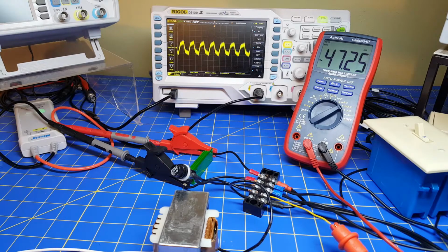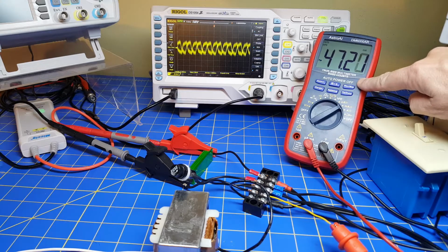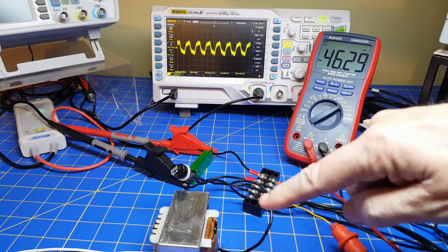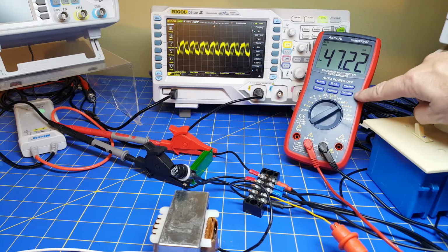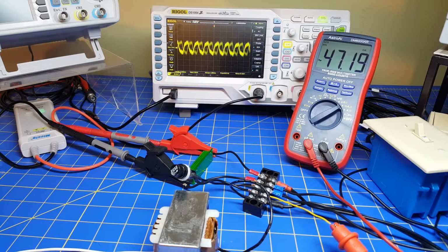We said we've got about 20 ohms of resistance, but with 120 volts and only 47 milliamps, you can tell this is going to be over 2,000 ohms of inductance. So again, both of them are fairly consistent, and they give us a good idea that we're talking about 120 volts and about 50 milliamps.